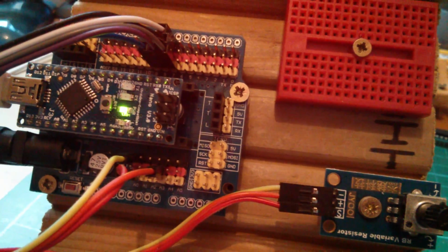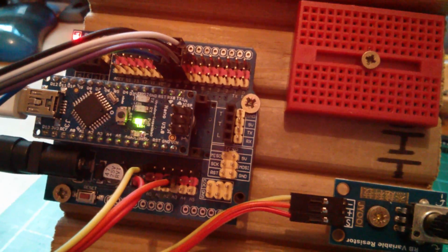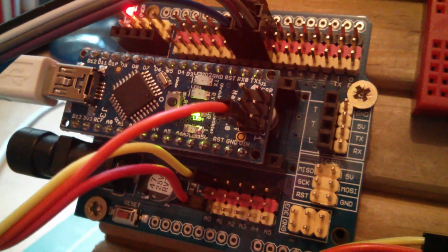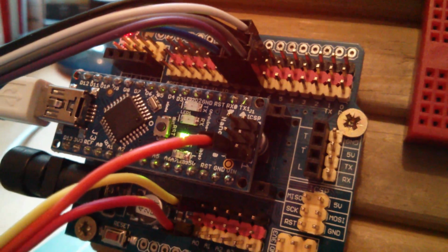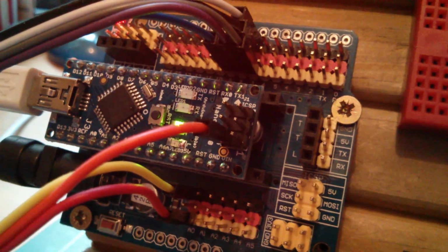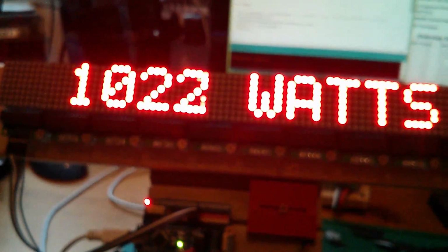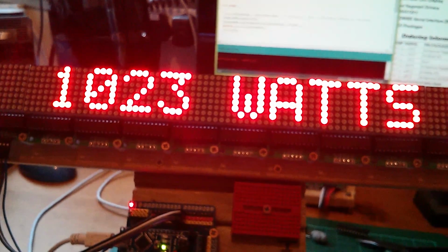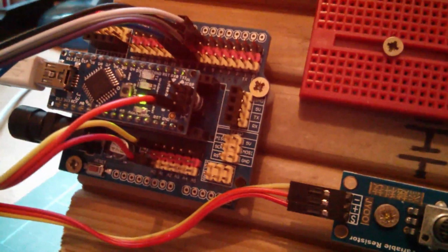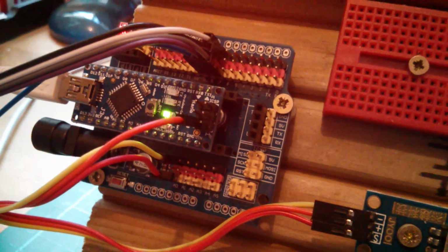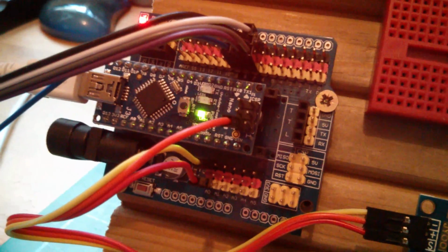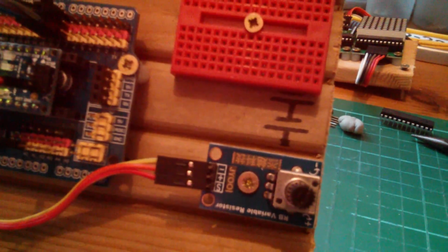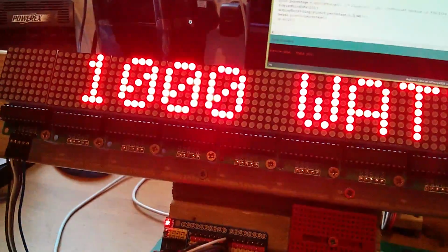Now look what happens when I move the positive connection of the potentiometer onto analog 5 volts. So I've moved the top of the potentiometer, which is actually that orange wire, to pin 2 of the ICSP header, which just happens to be analog 5 volts. And now on the display, we're getting a reasonably stable 1023. So it's fine if the potentiometer takes its 5 volts from the same supply that the microcontroller itself is referencing the analog measurements. Now I've turned the potentiometer down a little bit, and there is a little bit of noise.